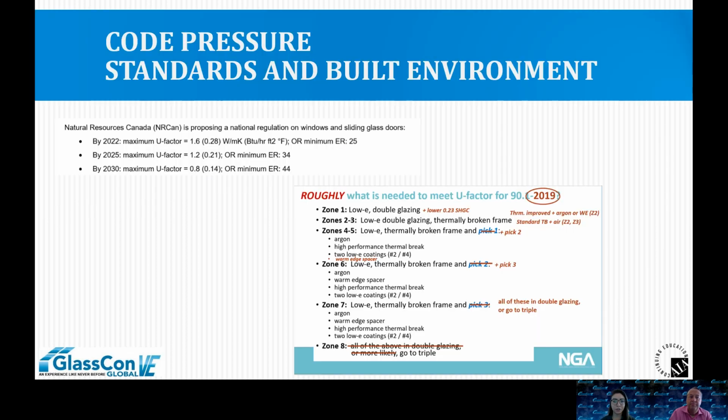If you look at energy codes from a national level down to a local level, maybe even to your optional programs like LEED, what we're seeing is that building energy performance is actually becoming a lot tighter. And we're seeing that since these energy codes being implemented are tighter, the window performance requirements are getting a lot tighter. A lot of this is hitting new construction, so we're seeing that window requirements are starting to exceed what's generally achievable through traditional IGUs.